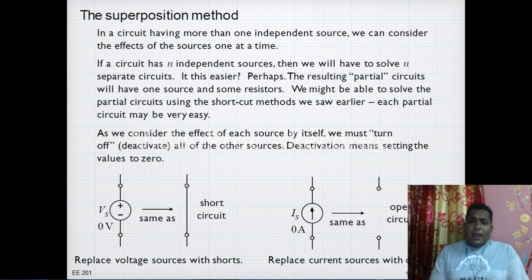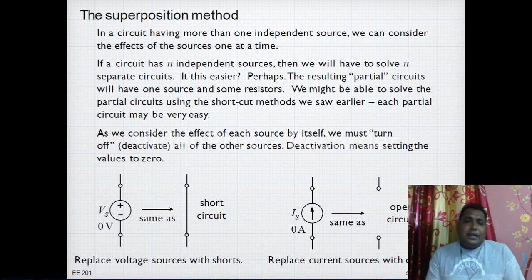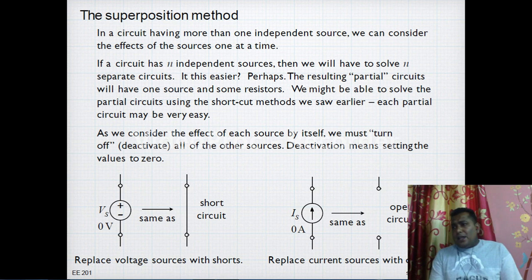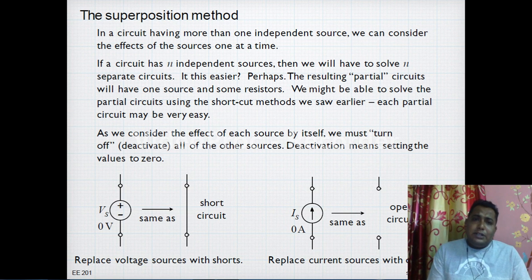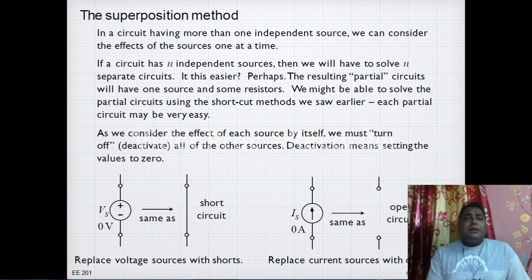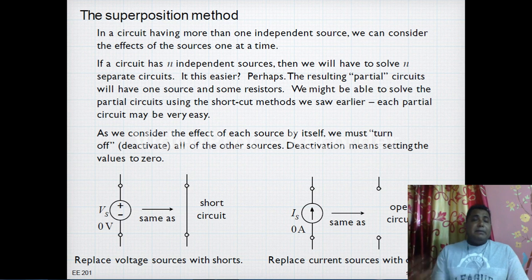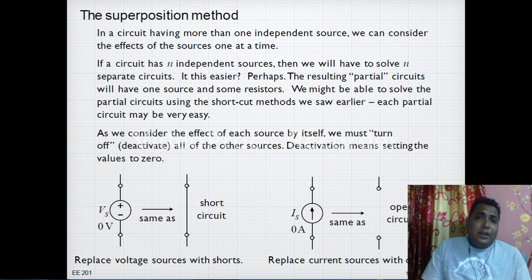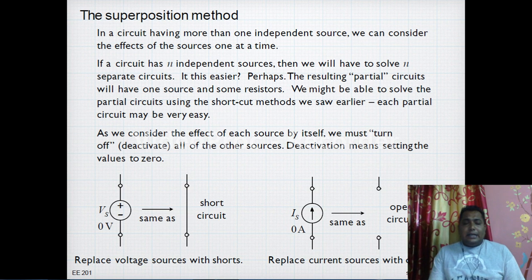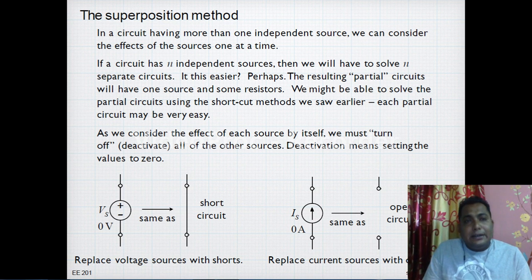And now we are going to see the shortcut method we have for solving any kind of superposition problem. When we apply the superposition theorem, we have to consider only one source and remove the others, maybe voltage, maybe current. When we remove a source from a circuit, what do we have to do with that terminal?